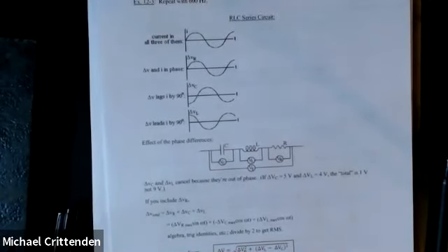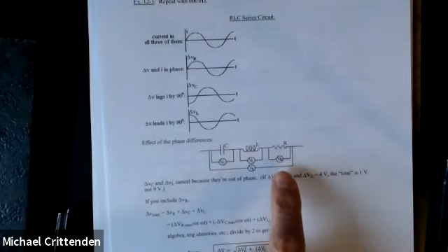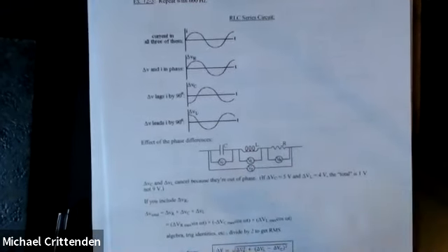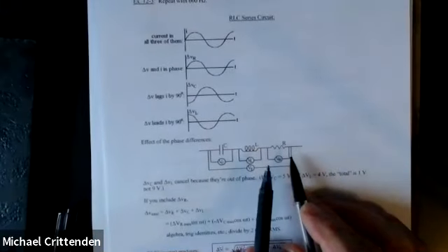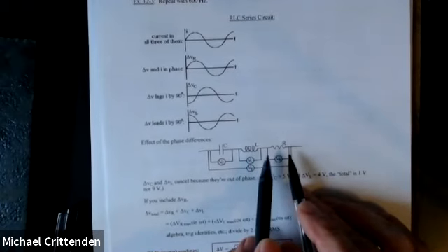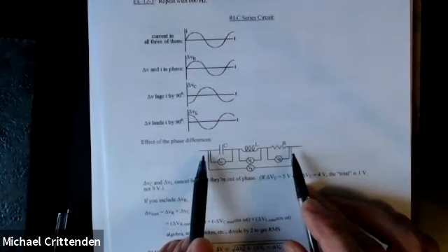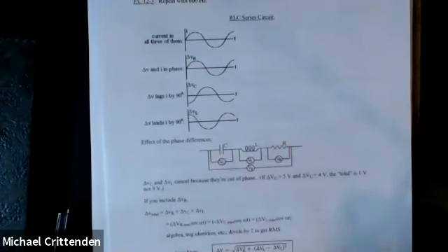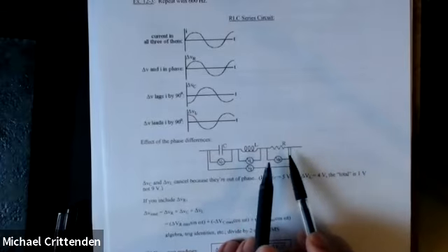How many amps flows? And people think, oh, Ohm's law, V equals I times R. But I times R is the voltage across the resistor. The voltage across the whole group corresponds to the number of ohms for the whole group, and that's the impedance. Resistance is just for the resistor. Okay.